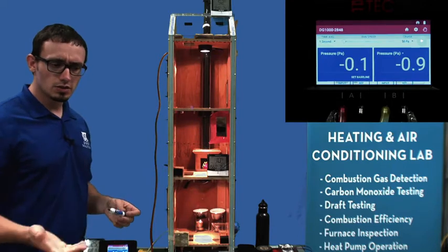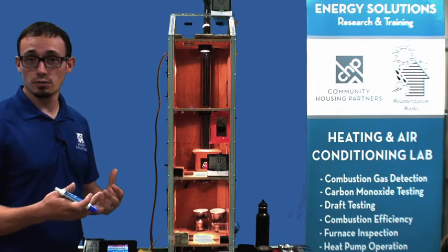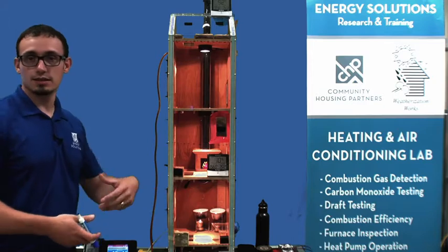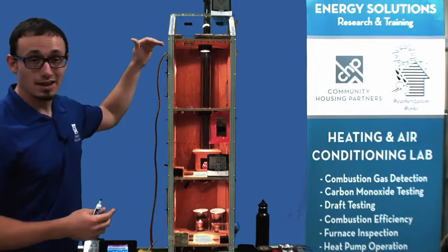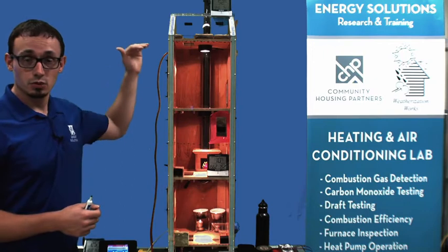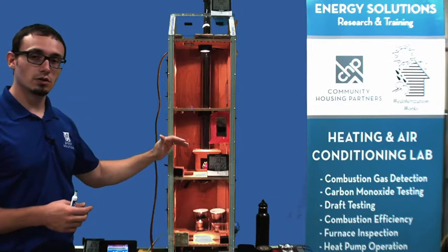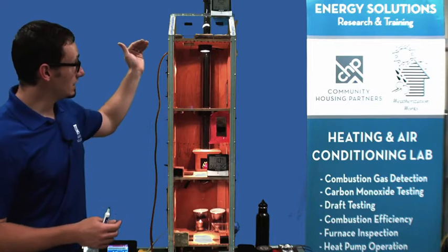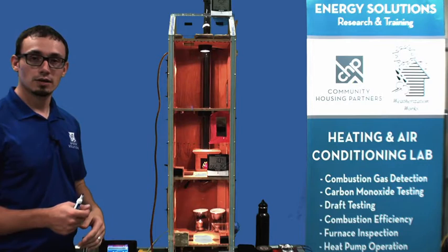So again, just to recap, convection is the heat transfer mechanism dealing with airflow and air leakage. Because that heated air has the tendency to rise up and out of the structure, I have to control that by sealing up bypasses in my ceiling and floor. If I have equal bypasses between high and low in the building, then my neutral pressure plane is going to be about smack dab in the middle, and I'll have a field of positive pressure and a field of negative pressure. If I seal the attic bypasses, I'll drive that neutral pressure plane completely down.